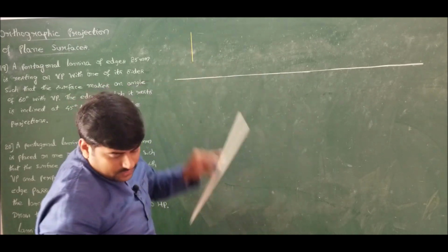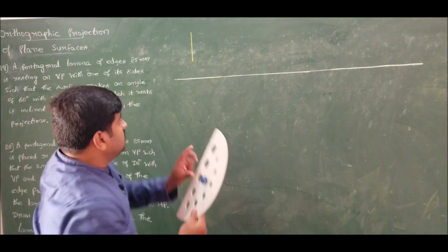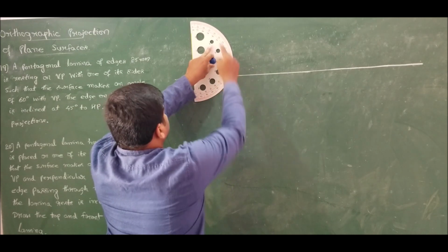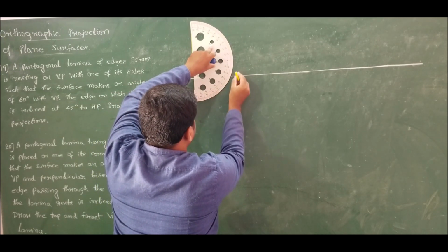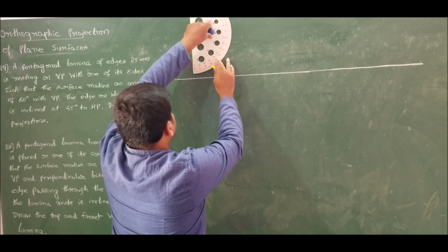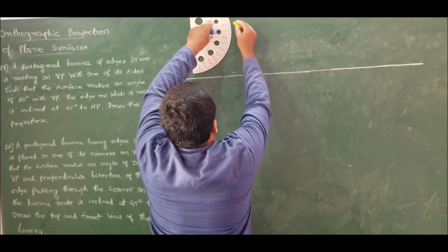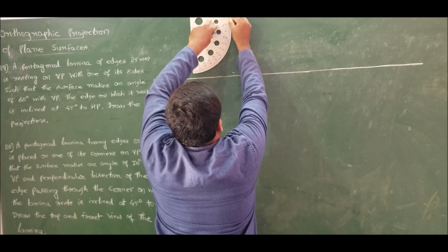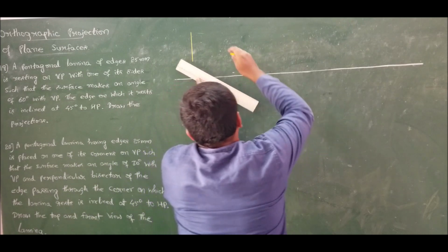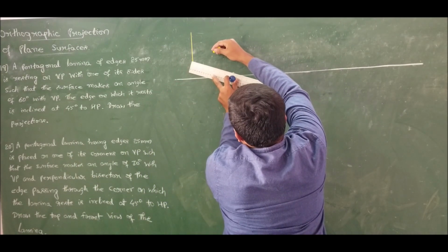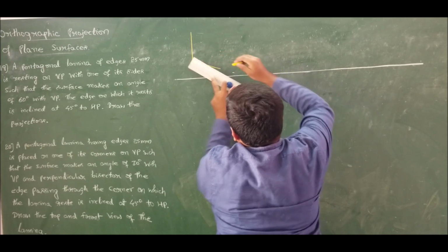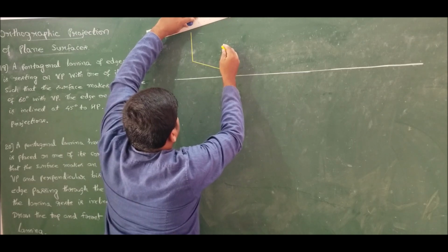Drawn. Now use a protractor and lay down the angle, either interior 108 or exterior 72. Similarly, above also lay down the angle, that is interior 108 or exterior 72 degrees. Done. Now draw the remaining edges. Edge dimension is known, which is 25 mm. Similarly, above also you lay down the edge.